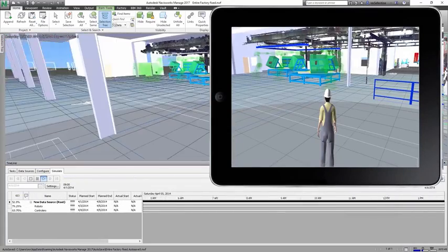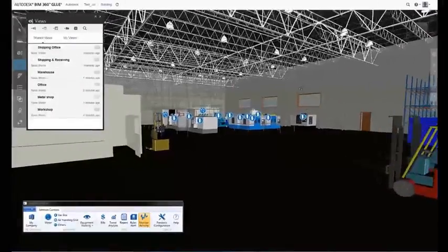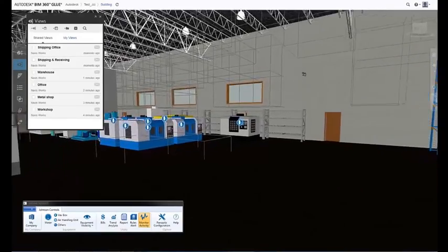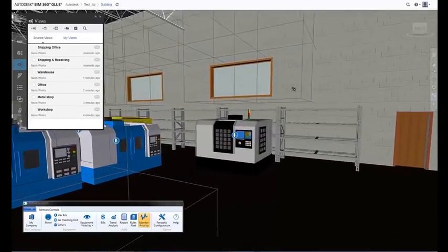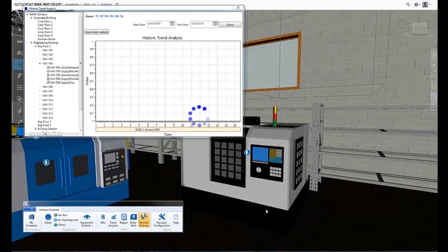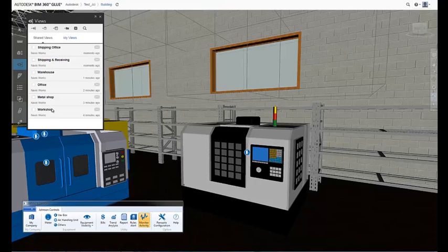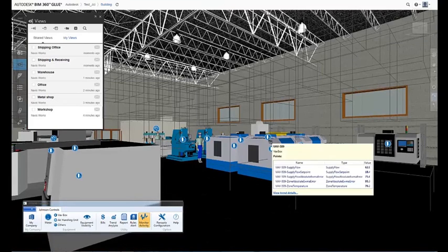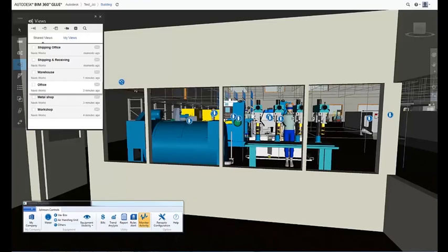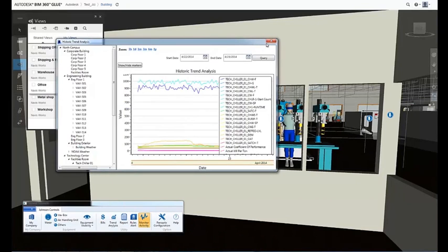After successfully ramping up the production, the integrated factory model is handed over to the owner or operator. In this phase of the factory lifecycle, we can leverage the integrated factory model by linking master data to the geometry. Master data such as processes, setup, and downtimes of the factory assets can be linked back to the digital mock-up. Maintenance engineers can leverage this to find the right spare parts, having all documentation at hand, and can make informed predictive maintenance decisions using historical data in combination with a 3D model.